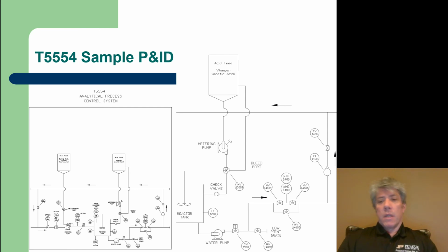Well, you have to understand something about analyzing pH. pH sensors, or the pH element, so you notice a lowercase p with an h together, those two indicate the variable being sensed. P by itself would be pressure, and it would be an uppercase thing.